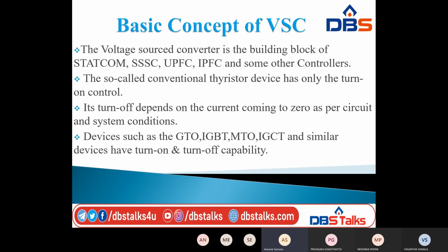The so-called conventional thyristor device has only turn-on control. If you use the thyristor as a conventional control device for the system, it has only turn-on control. Its turn-off depends on the current coming to zero as per circuit and system conditions.